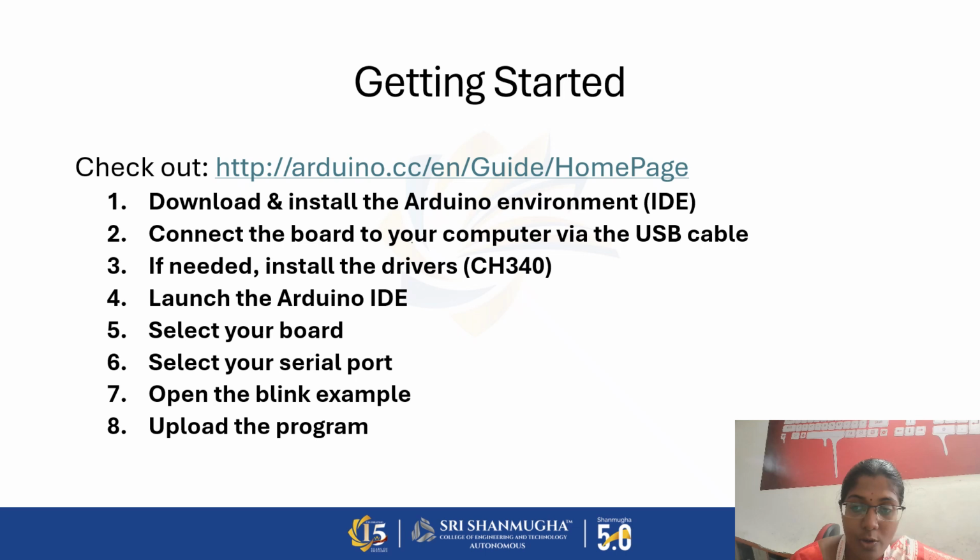If it is already installed in your computer, there is no need to install. If it is not installed, you have to download and install the CH340 driver software. It is also available on Google itself. Then launch the Arduino IDE, select your board, and select your serial port. For example, you can open the Blink example and upload the program.